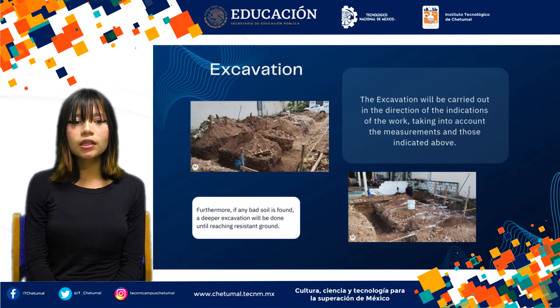The continuous footing is another commonly used type of foundation, especially for structures with continuous load bearing walls. Unlike isolated footings, the construction weight is distributed continuously along the ground. Use and characteristics. Continuous footings are ideal for buildings with bearing walls, like traditional houses. They are also used on low strength soils where it is necessary to distribute the load more widely.